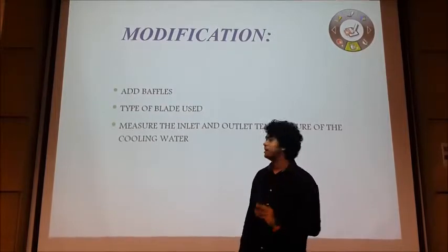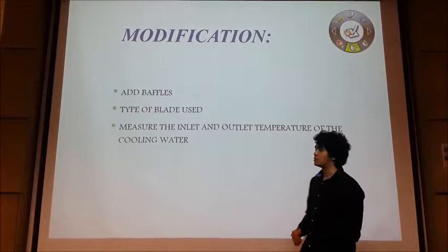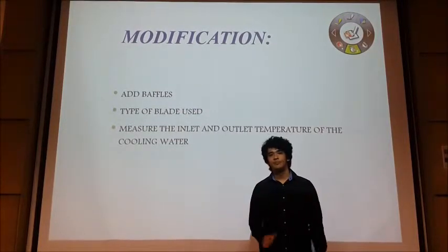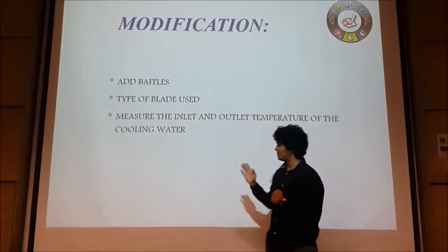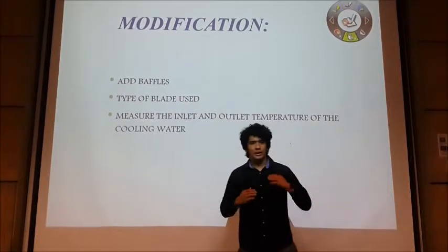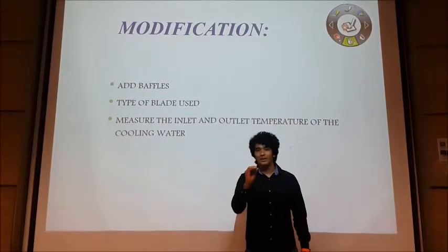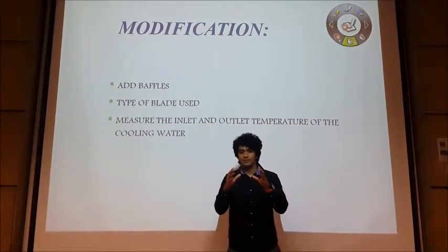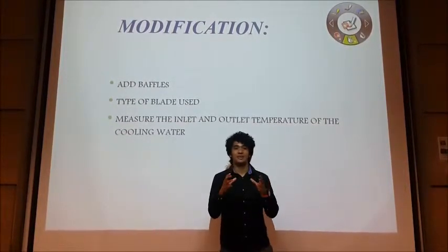It's almost the same. Last thing is, we should measure the inlet and outlet temperatures of the cooling water. Alright. This step is important so that we can know the right amount of temperature required just to cool, to take out the right amount of heat of the exothermic reaction.